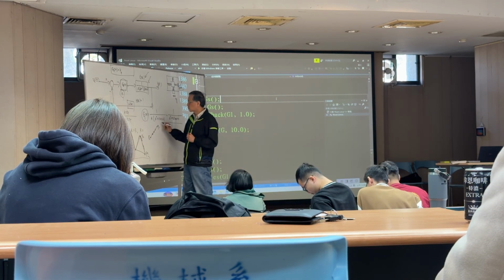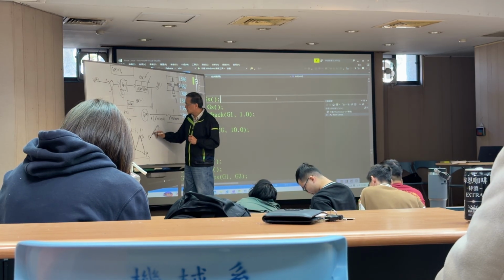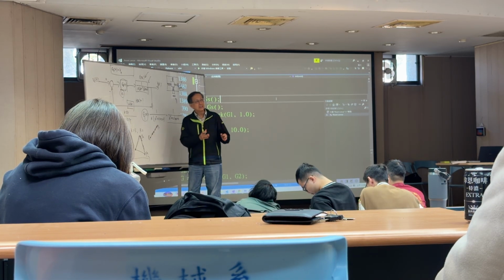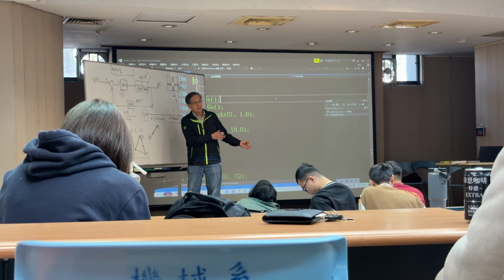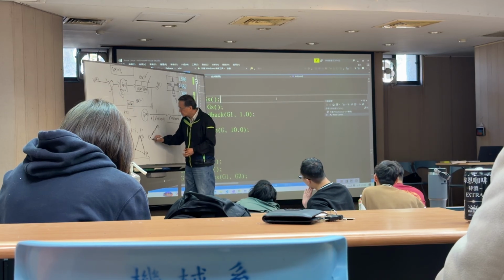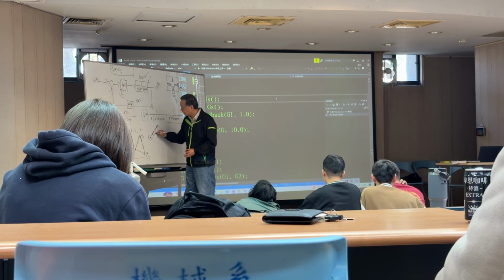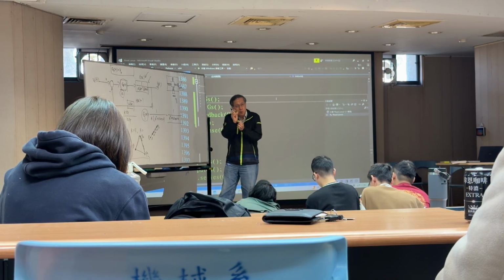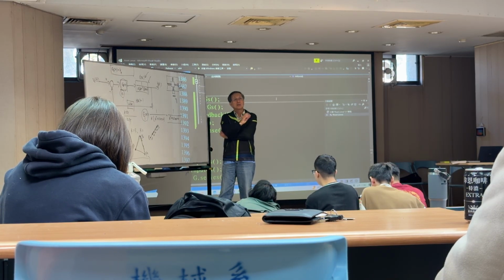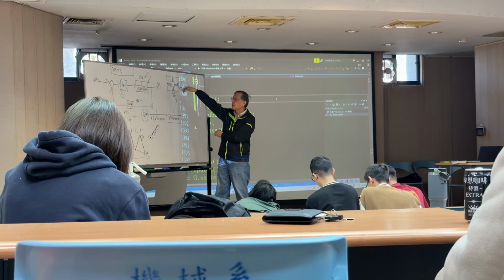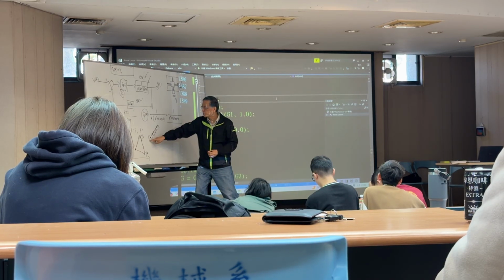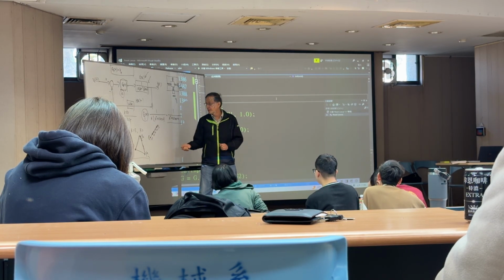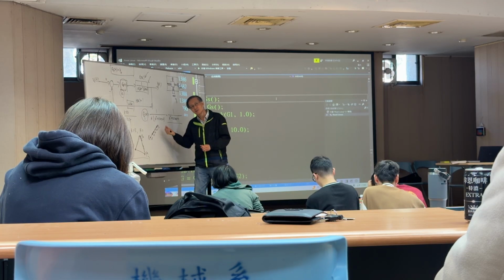Remember, even though this is a straight line, the controller is actually still moving in small linear segments. Remember I said that? They are moving in small delta s, small delta s, very small, tiny segments. The controller, the machine, the XY table, they are not moving like P1 to P2. No, they are moving in small linear segments.